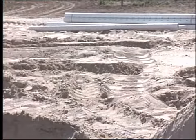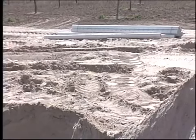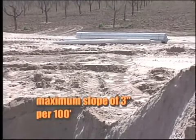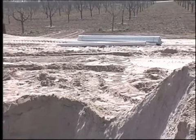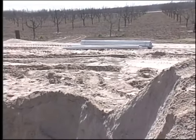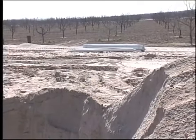Then level the gravel before you place the pipe. Lay down a 4-inch diameter perforated pipe on a maximum slope of 3 inches per 100 feet. Pipe for the distribution lines must meet local and state specifications. Do not use coiled perforated plastic tubing because the tubing will not maintain the slope or lay flat.